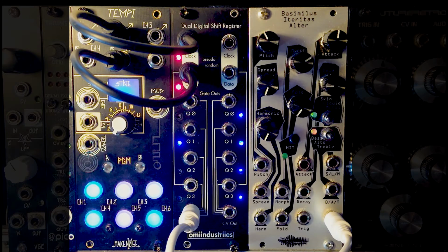That means the data input will be high if one or the other signal is high, but low if both or neither are high. The 4 stages are summed together using a digital to analog converter and output as CV. The width of the clock signal doesn't matter, as the module only looks for new data during the rising edge of the clock pulse. The data needs to already have been high when the clock goes high for the shift register to recognize it as a high signal.